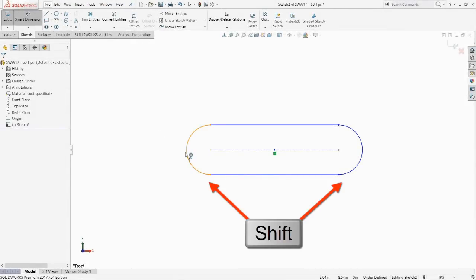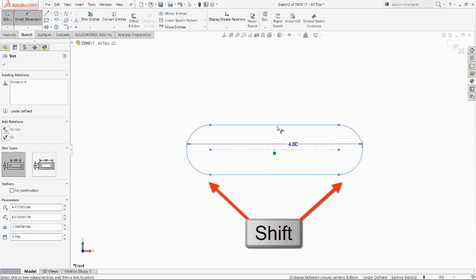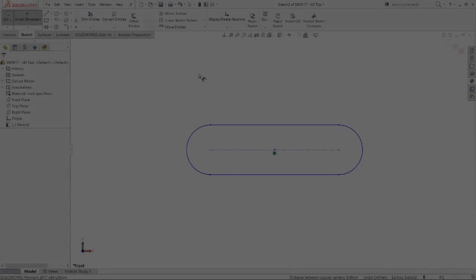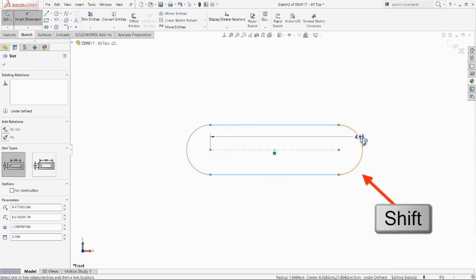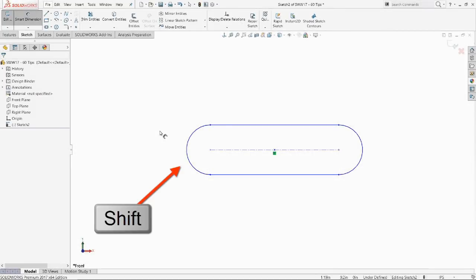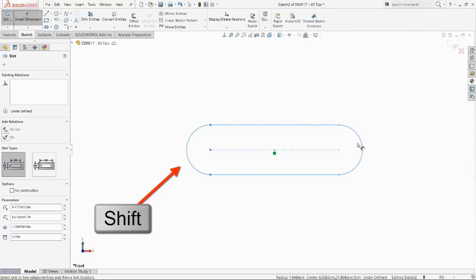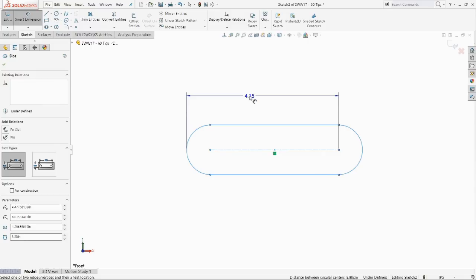So now we're starting to add these on the fly. We're holding the shift key to pick both of those, right? Now I'm going to just do the shift key for the second one. So it's going to go to that first arc center, and now it's going to go to the tangency here. But now I'll do shift, and it's going to go both. Shift, not shift. Right, so I bet most of you knew that, but for the people that probably didn't, it's very helpful.